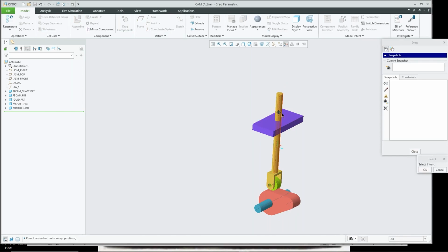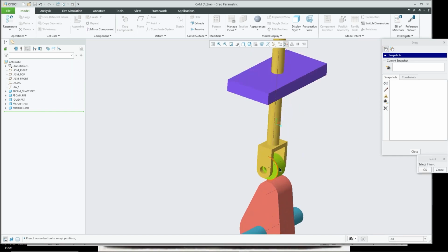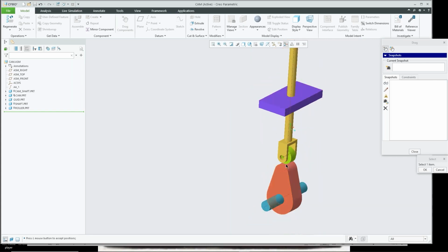it won't go above. Because of the connection between this roller here and this shaft, and because of the actual cam connection between this surface and this surface, this can't move off of here, which means this can't move out of that axial constraint. So it has to stay locked in that way. So I can't move this off of or higher than this connection will allow it. So there's no way to disconnect those.